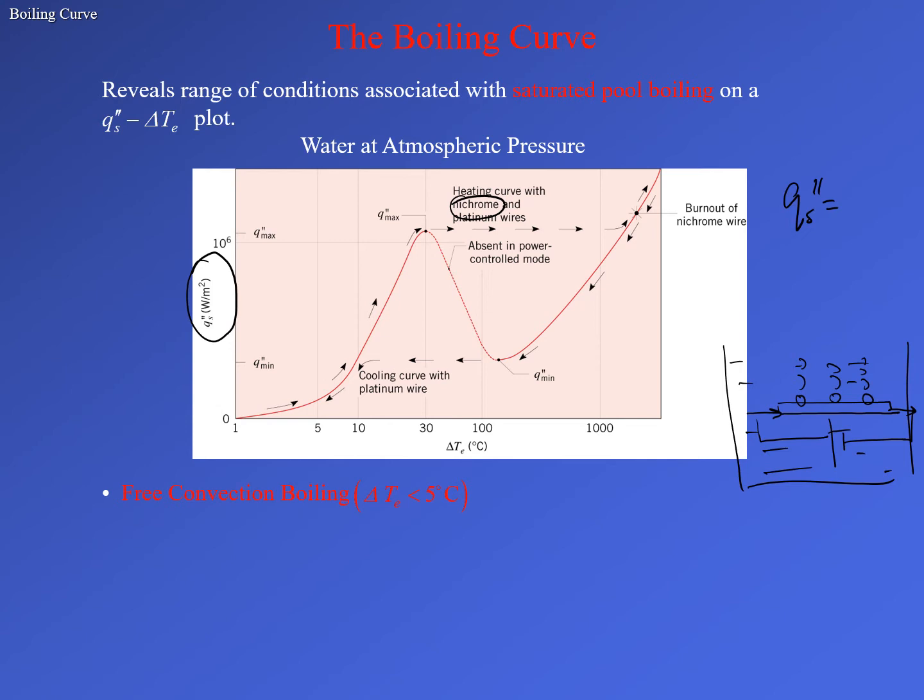The watts is the electrical watts, so you can multiply your potential difference by the current through the wire. All the energy that is getting released from the surface of the wire has to leave as convection. We are neglecting radiation right now as well as conduction. So almost all of the energy from the wire is leaving as convection into the liquid.